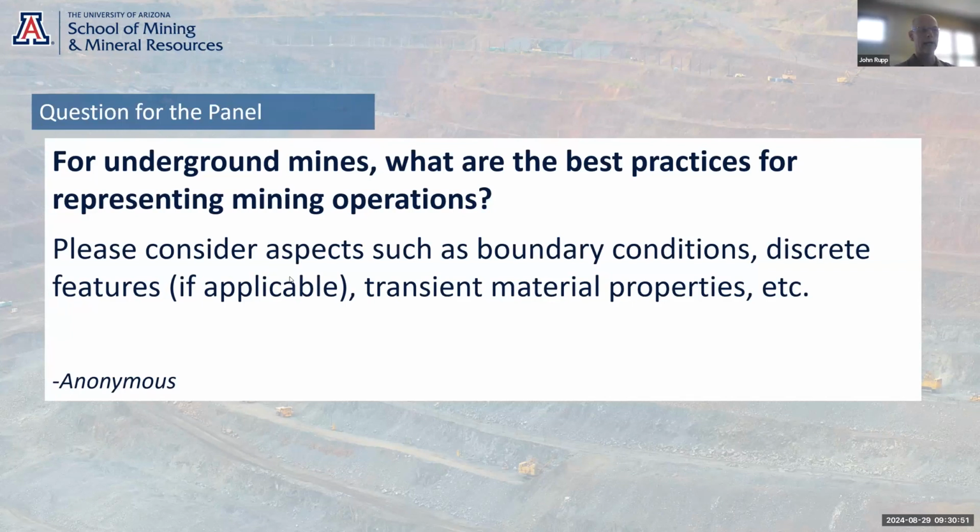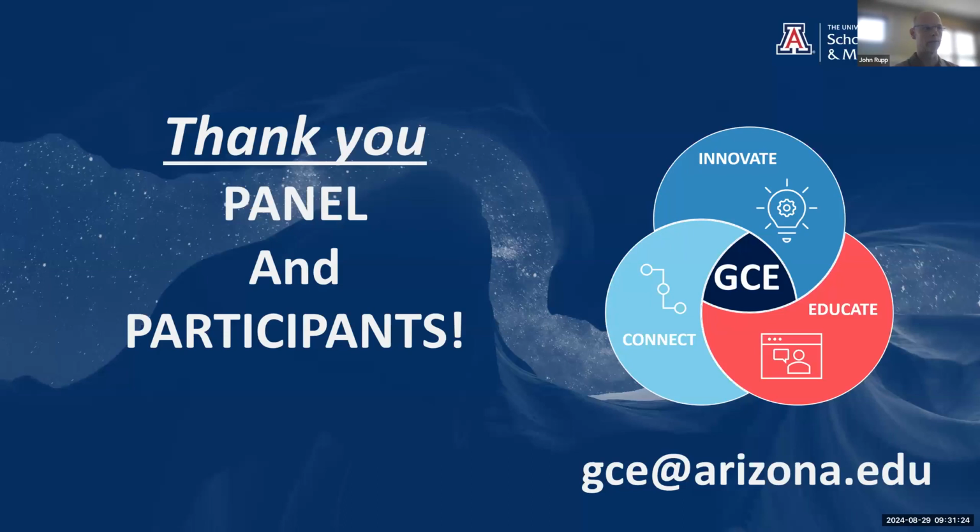You want to make sure that you're capturing the evolution of voids from the native rock to a void space, and then also any backfill that's going to happen. And you don't necessarily have to include those as transient material properties. You can break that up with your predictive simulations. The bottom line is, though, you've just got to make sure that your hydraulic response to whatever you've applied makes sense. You have different choices, and when you apply those choices, you have to verify that the model's working.